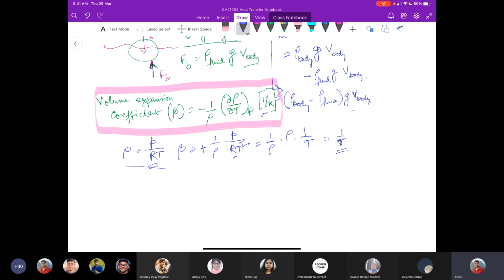And we have seen in external flow cases that when you increase the flow, in the turbulent region, the thickness becomes thinner and thinner. So if you decrease velocity, it becomes thicker and thicker. And here there is no external flow, so it would be somewhat greater than the forced convection cases.